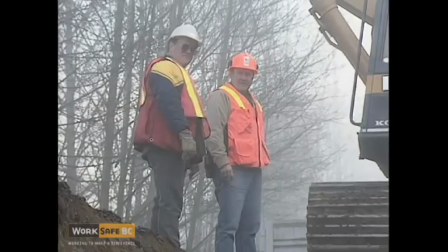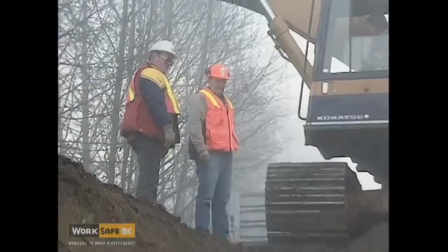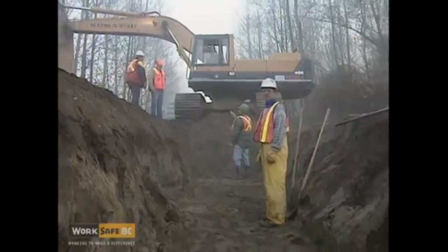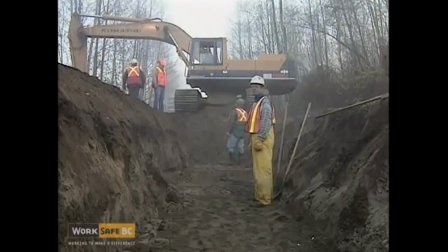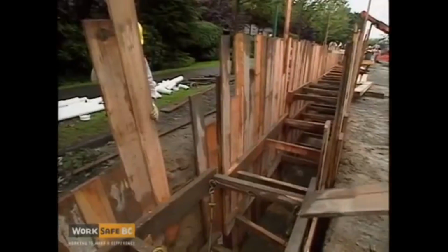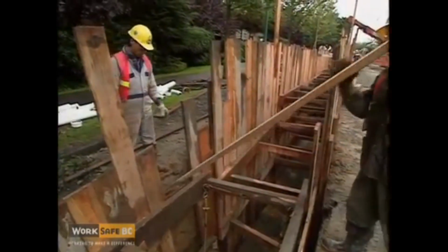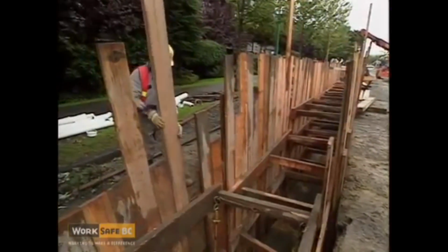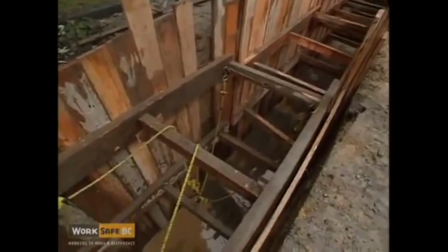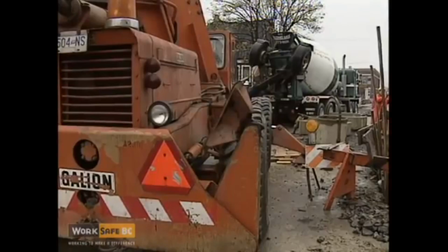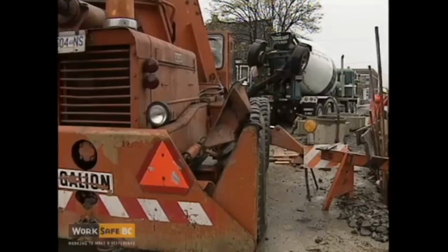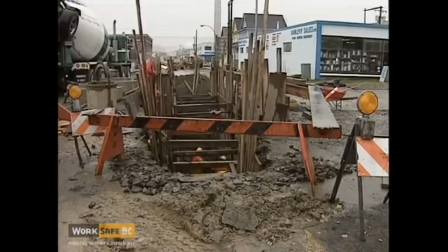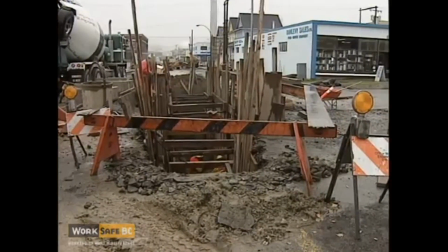Workers shall not enter any excavation over 4 feet in depth unless the sides of the excavation are sloped to a safe angle. The sides have been supported by the use of sheet piling or shoring and bracing, meeting the minimum standards contained in the regulations. Or the workers are protected by other effective means, such as restricting worker access to the hazardous area.